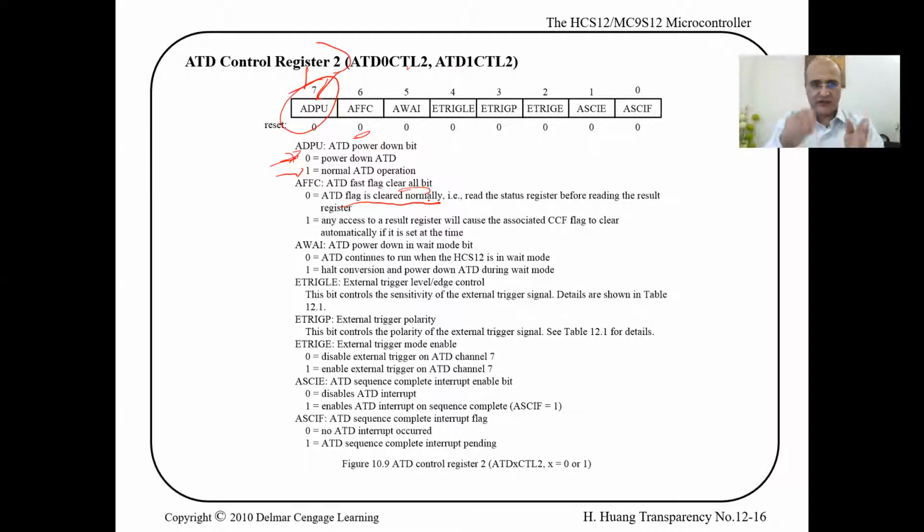This thing takes time, in addition to the time for sample and hold. So it's not like in 0 seconds you say read the A to D and you got your result. It takes time. So how do you know that you are done reading the analog voltage? A flag will be raised for you, or an interrupt will happen. This flag needs to be cleared when you're done. Okay.